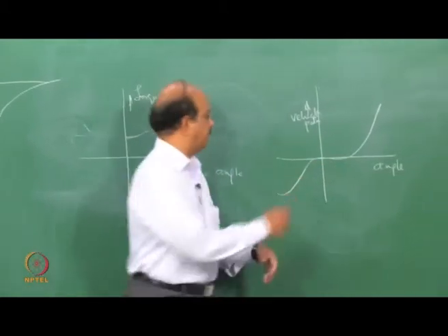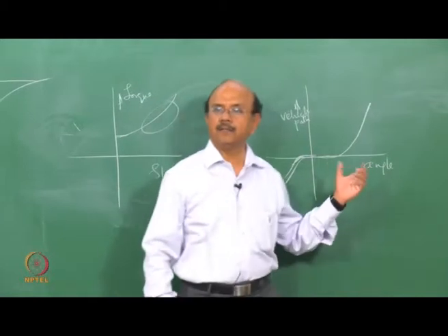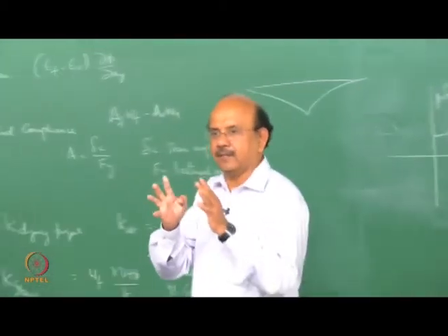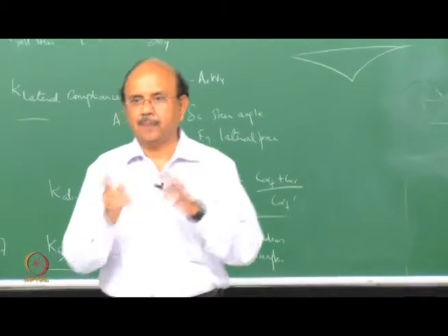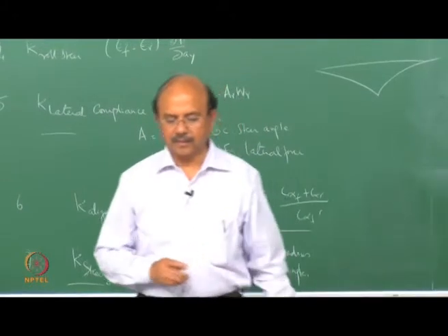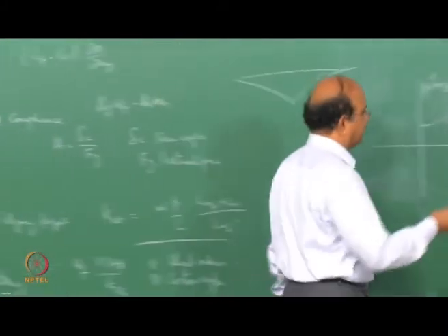Let's say that it's symmetrical about the center. You would see that there is an angle of the steering after which a path change is going to take place. This is very important. This is called the dead length.